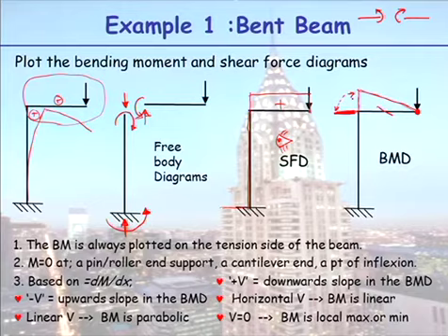So going around a corner, the moment in one leg always equals the moment in the other leg. So I do have a moment in here, because I can see I've got that vertical leg curving. But according to my shear force, it is 0. So if my shear force is 0, that's telling me the slope of my bending moment is 0. It's not telling me the value of the bending moment is 0, it's telling me the slope is 0. So there you go. That means my bending moment in here will be constant.